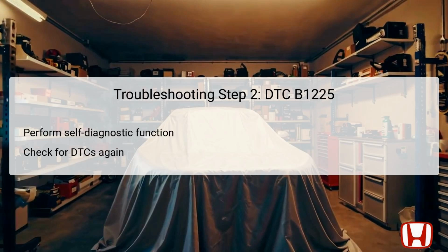In this second step of the troubleshooting process, technicians will perform the self-diagnostic function using the HDS or through the climate control unit. This self-check is essential to identify any persistent issues that may not have resolved with the initial DTC clearing. After conducting this diagnosis, the next step is to check for DTCs to see if any codes reappear. If DTC B1225 or the A and auto indicators are displayed again, this signifies the need for further investigation into the in-car temperature sensor circuit.